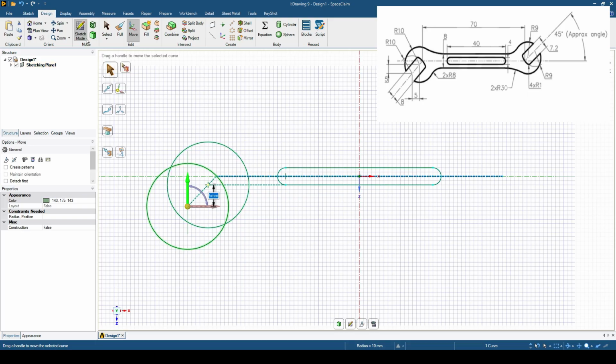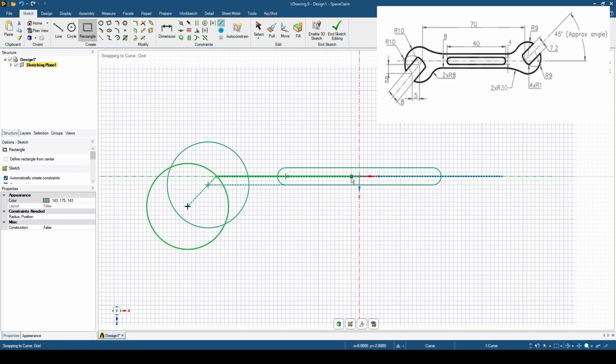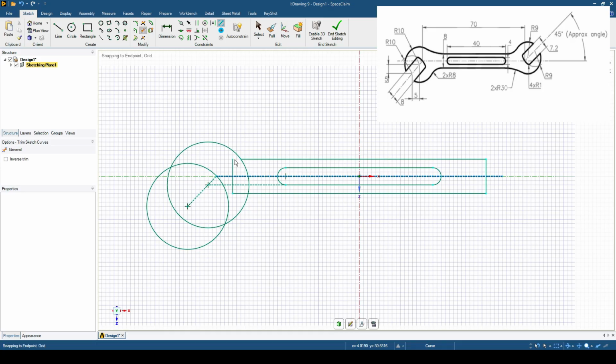I'm going to draw the bigger rectangle, choosing Rectangle from center, then going to the center. I'm going to make this intersection. The important thing is it should have a height of 8 millimeters, so 8. The length should at first be at least inside this circle that we already drew. So let's click Enter, and now let's trim these extra lines there, and let's remove these.